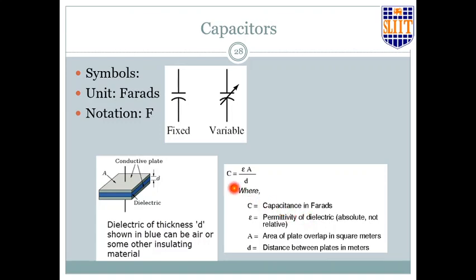And the other is the distance between the two plates, which is actually the thickness of the layer in between. Now, ceramic has a very high dielectric constant. However, you can't roll ceramic into a very thin layer. You can make a very thin layer, in the micrometer range, from polythene or paper.